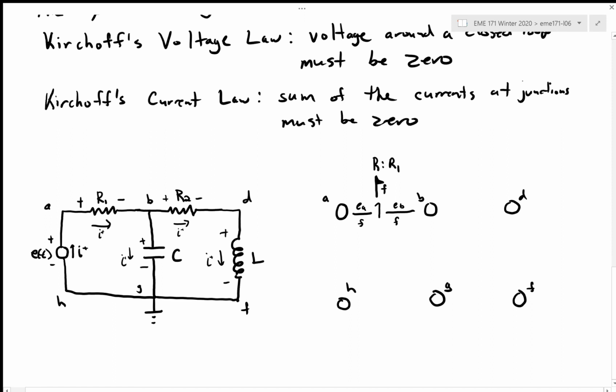I want to ensure that we see a voltage drop here for my sign convention, and that would mean that we want EA, the voltage on the A side, minus the lower voltage on the B side to give us a positive value. So I want this to be EA minus EB.